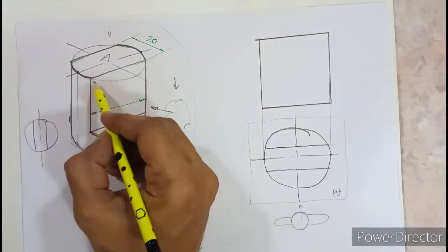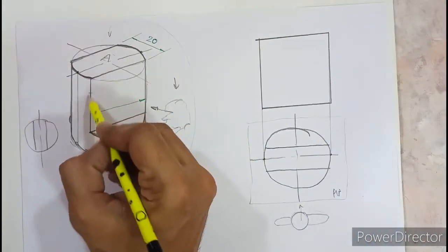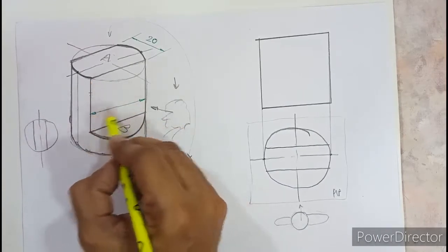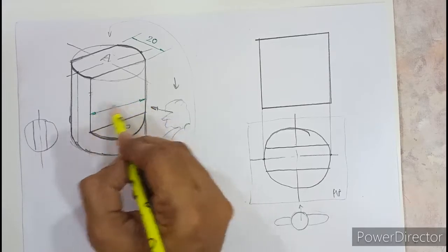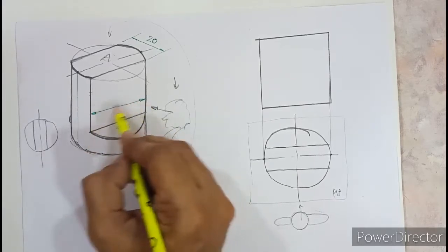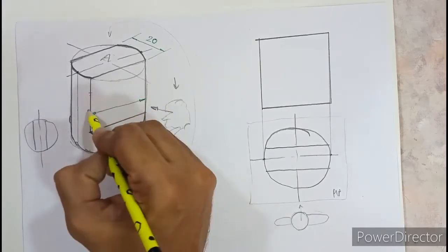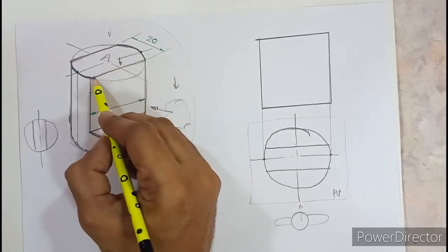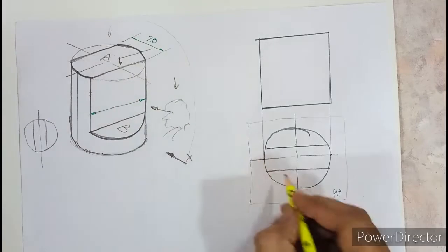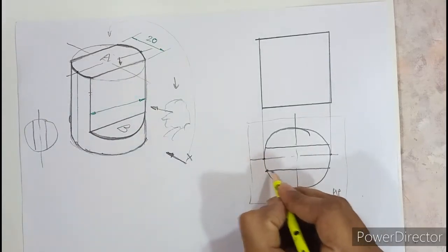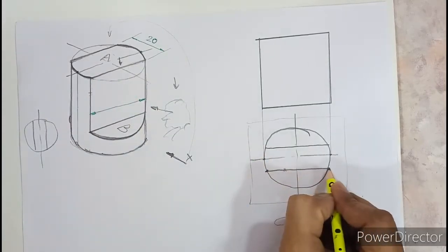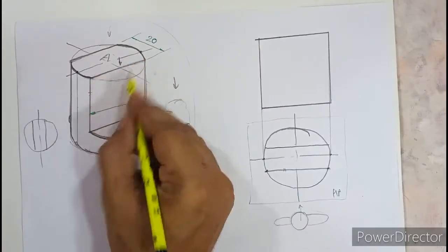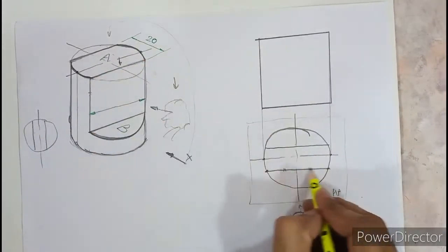But apart from that, I can also see an additional dark edge, which is away from here. This dimension is not given, and it is neither a printing mistake. So if you try to visualize this edge from the top view, you can get the answer. So try to find out in the top view, where is this edge? Yes, so that edge is from here. It is this one, right? It is from here to here. See the same edge. This and this are almost same. So that edge is over here.